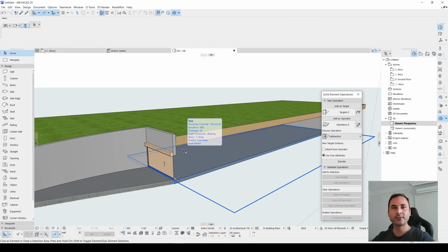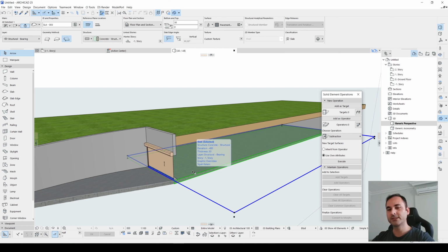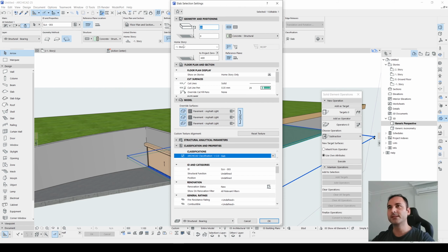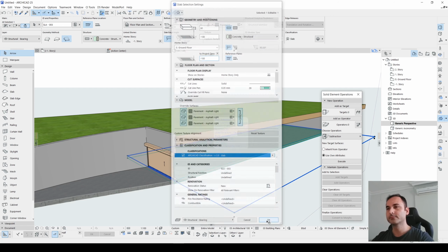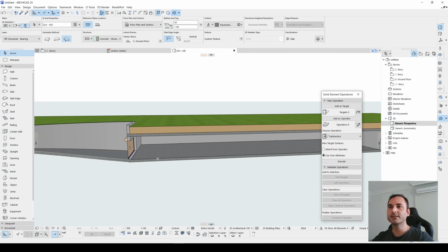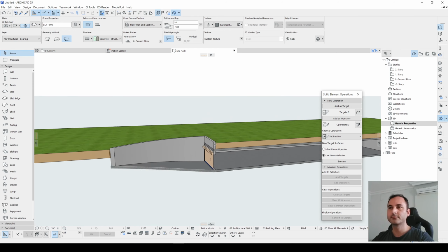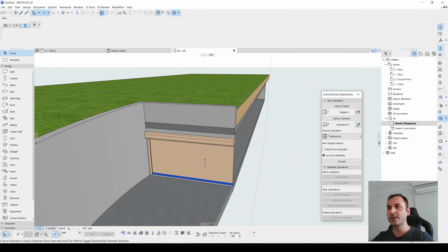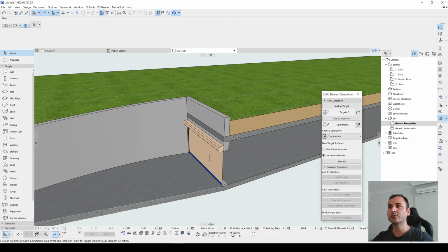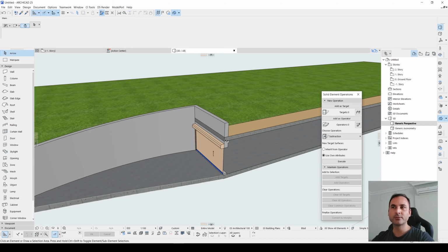Don't worry, I haven't forgotten to place the top slab. Let's click it and copy to same place. From the settings, let's make it from ground floor. And project 0 will be -100. Just like that. This structure seems incorrect, but it's true. First, they will place this slab. After that, they will start building exterior walls.